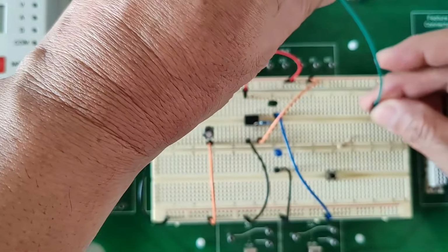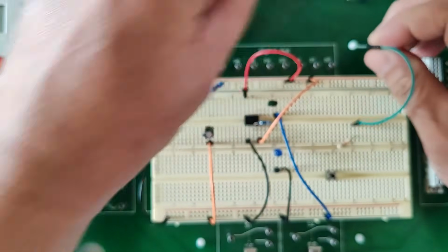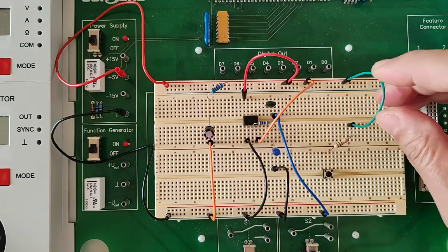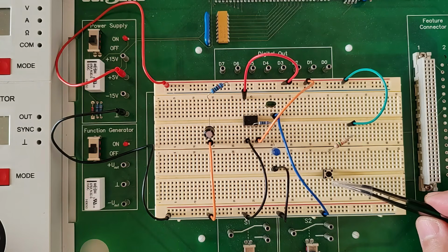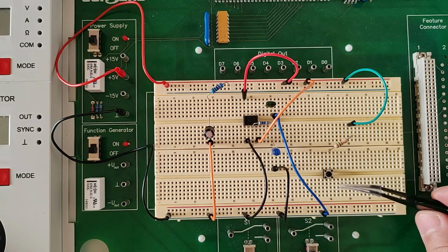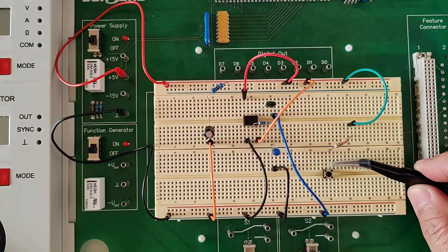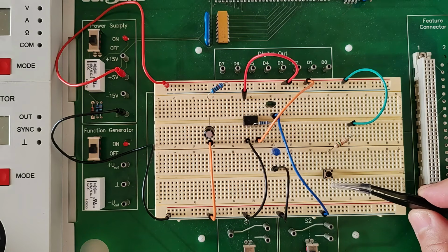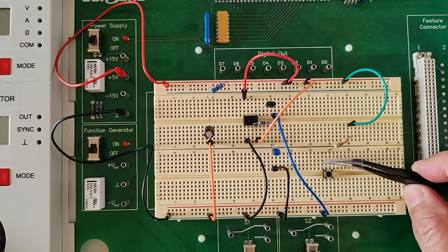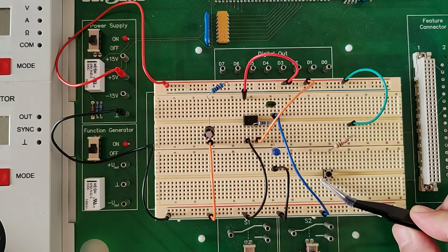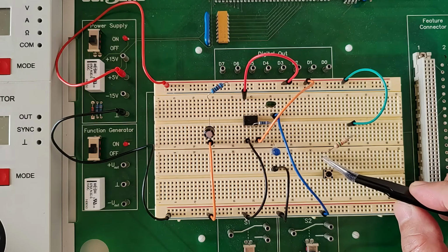Let's do that now. 5 volts. There. Connected to 5 volts. Now, to establish a connection to ground, because we need to ground also this tactile switch, I have a choice. I could either use the top right pin or the bottom right pin to connect to ground, because these two pins are not connected to the upper left-hand pin here. I cannot use this pin, the lower left-hand pin, because this pin will be connected to that leg of that resistor.